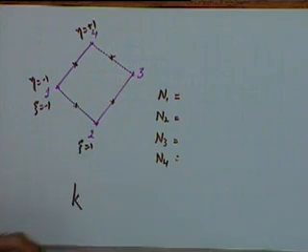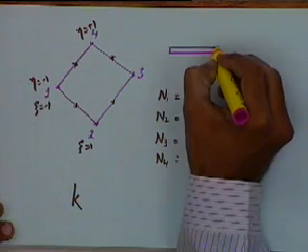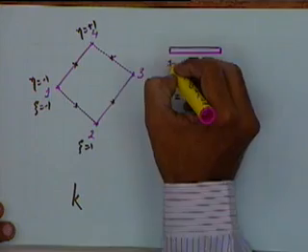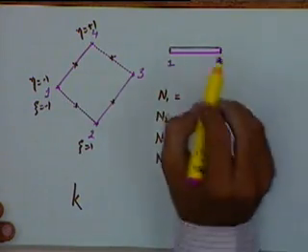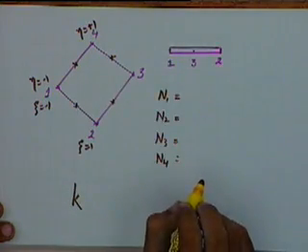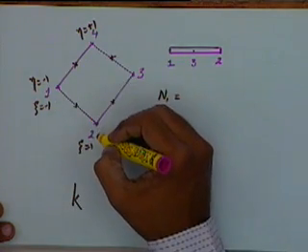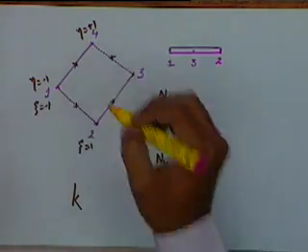Okay, the advantage that we will have in this is that, if you remember earlier when we were talking of a one-dimensional problem, we had a 2-noded element and we were doing linear interpolation between these 2 nodes. Then we went for a 3-noded element and we said we will do quadratic interpolation between these nodes. Similarly, now we will go for an 8-noded element and we will try to do a quadratic interpolation. The way we will define an element would be something like this.